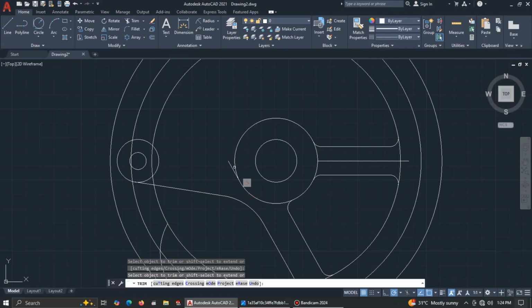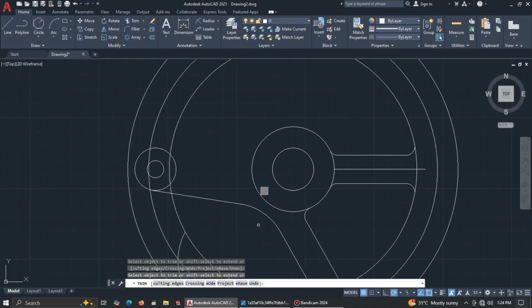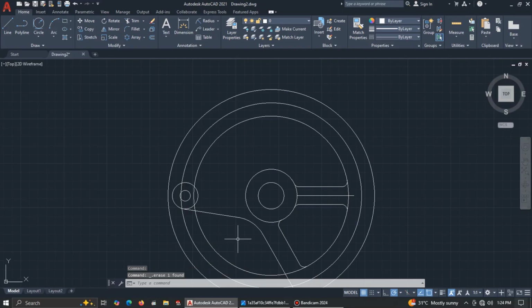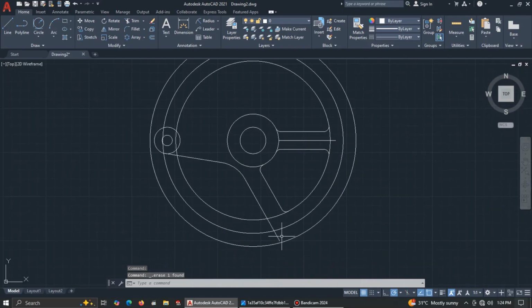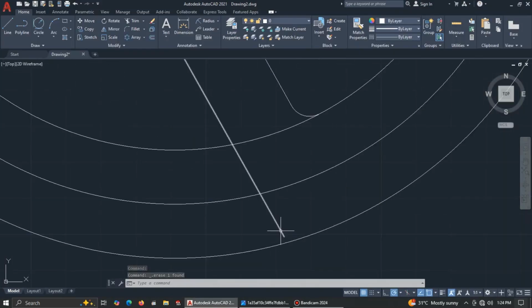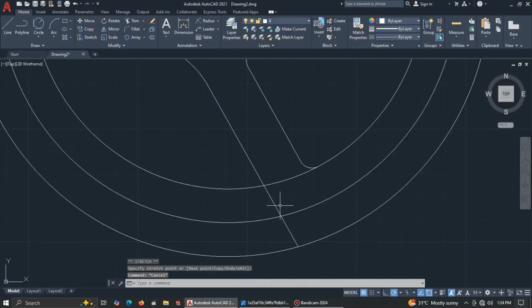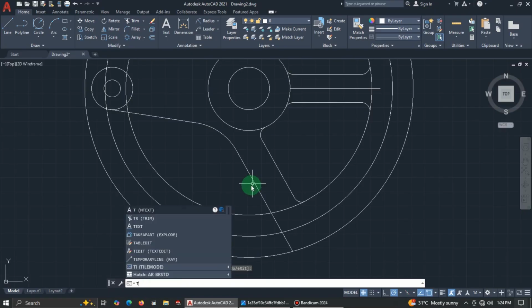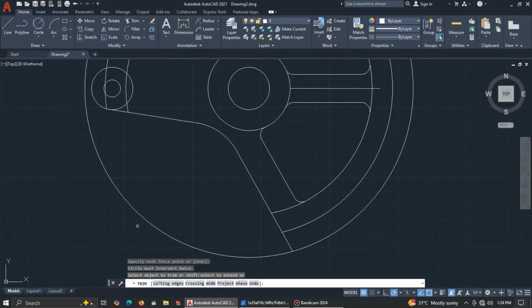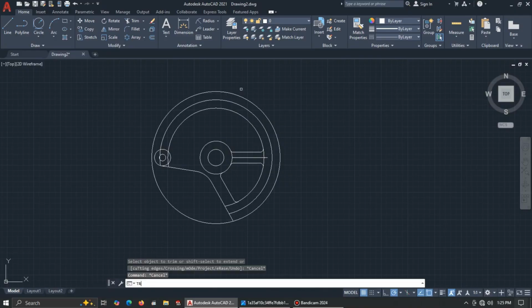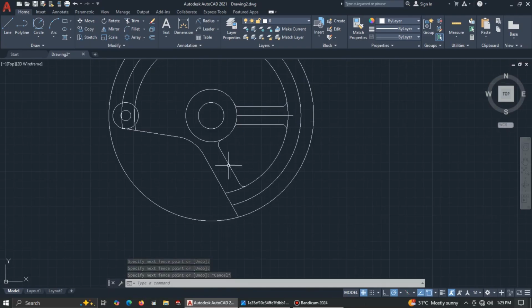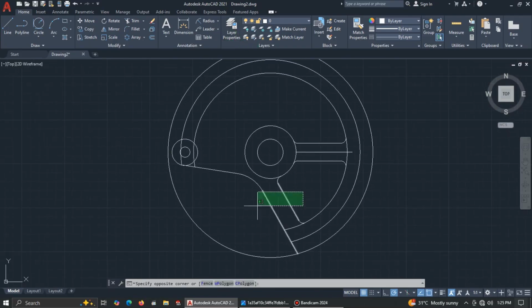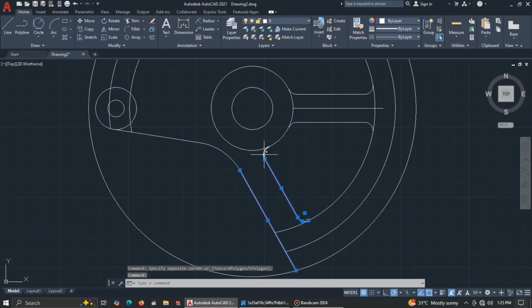Let's carefully delete the unwanted lines. Okay, and then here we check, this should be meeting this. All right, now we need to trim. Let's trim this one. Alright, so let's leave the top. Now what we want to do is we want to mirror all these features to the other side. Okay, so let's select all of them.